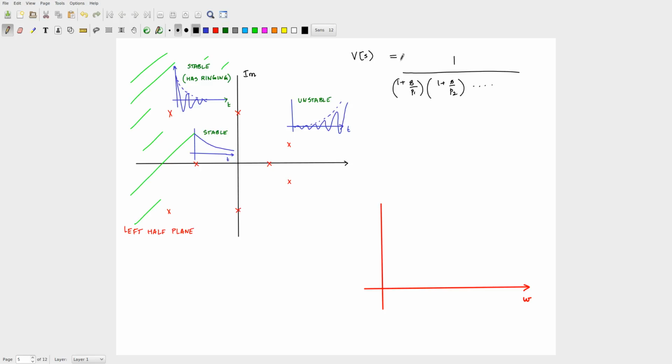What are we plotting in the frequency response plot? The frequency response, what do you plot? The 20 log and all of that is okay, but what is the essential quantity? V of j omega, right? It's not V of S, it is V of j omega. You plot it on a log scale, you multiply by 20, all of that, that's okay, but essentially you're plotting a quantity which is V of j omega, correct? And you have this pole zero plot.